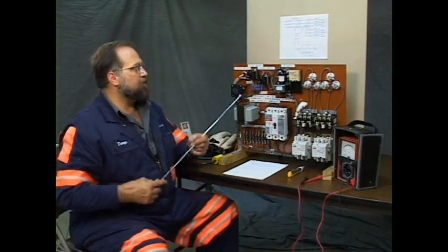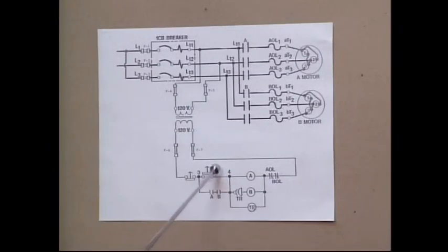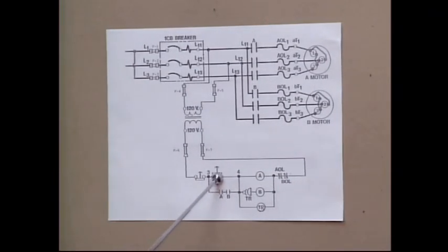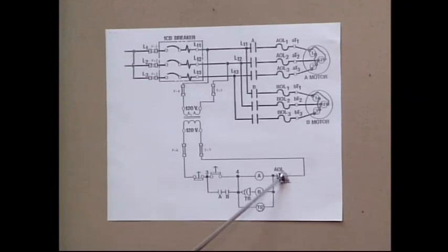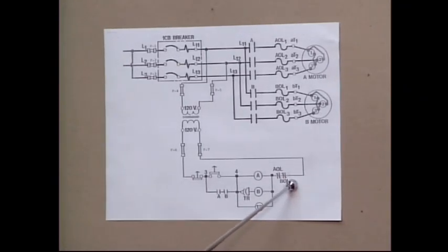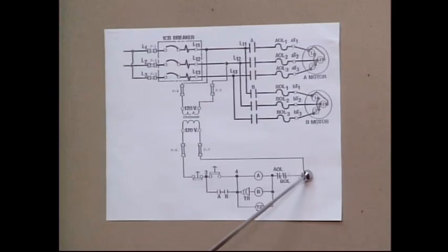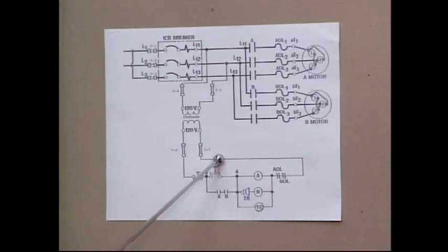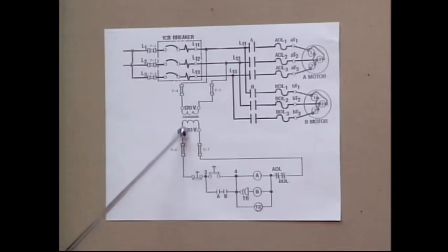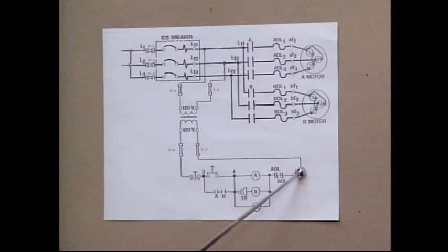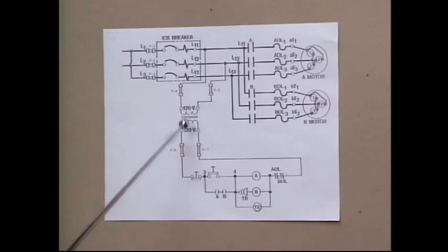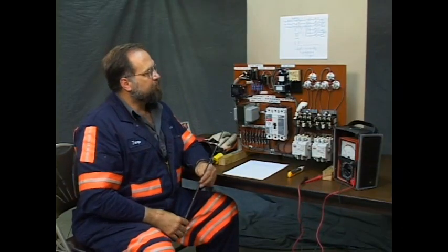Let's look at our map here. Let's see a print. Okay, we pushed the start switch. A went. We had power to A. Went through the overload switches. They're normally closed on AOL and BOL. Those micro switches were made. It went back to the transformer. We have a circuit. It went to it, through it, and then back away from it. We have a circuit. It's complete.